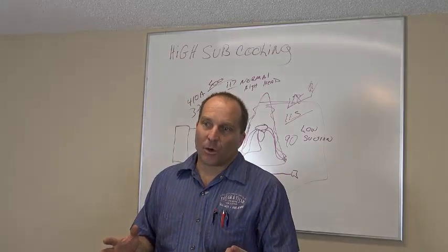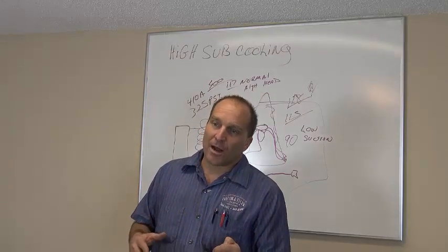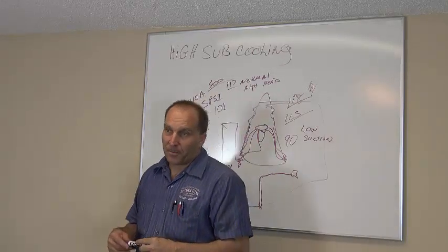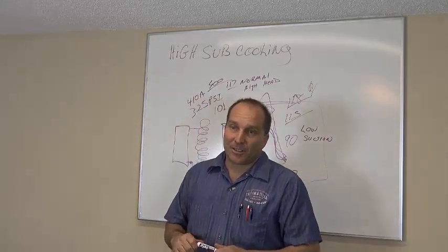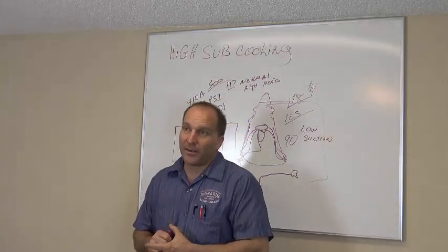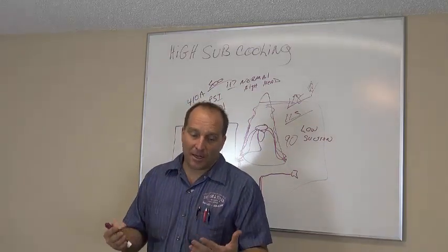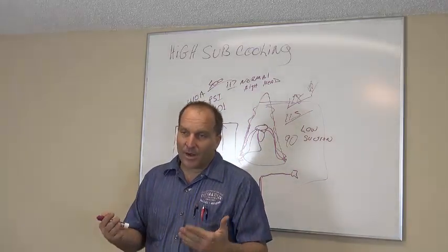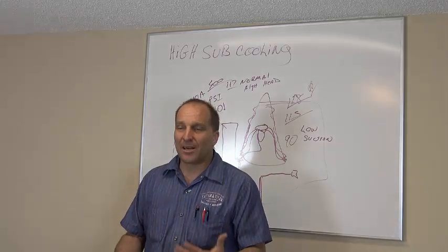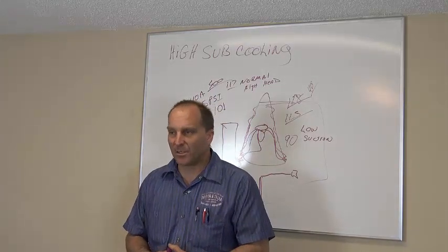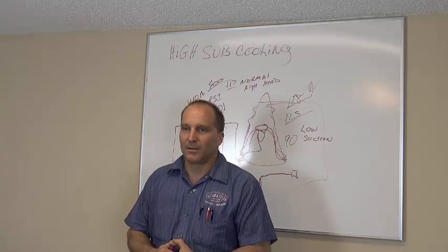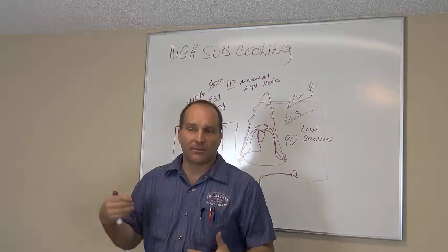Okay? So I want you to think about this when you're going out and doing the maintenance contracts. I had a technician last year that would continually bring me invoices, and I'm looking at them and I'm going, you're not cleaning the condenser coils. Tell me why you're not cleaning the condenser coils. He says they're not dirty. So he's bringing them left and right, left and right.